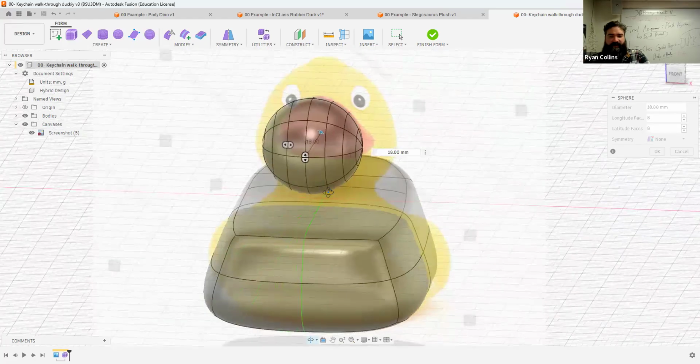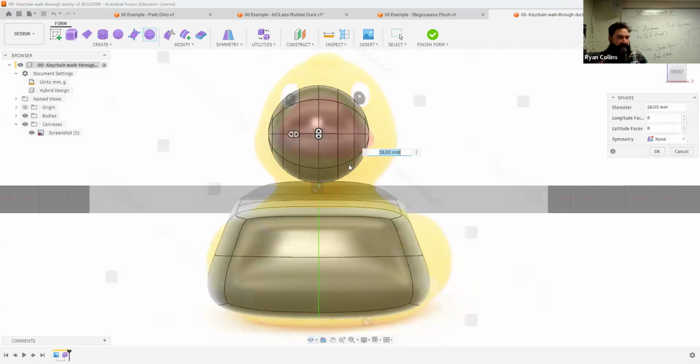If you accidentally selected one of the other planes and your poles are facing straight along, that's okay. You can simply move that. So we'll do that in a minute. But while the tool is still up here, I'm going to apply symmetry. Go to mirror. I want height. The green lines match up.